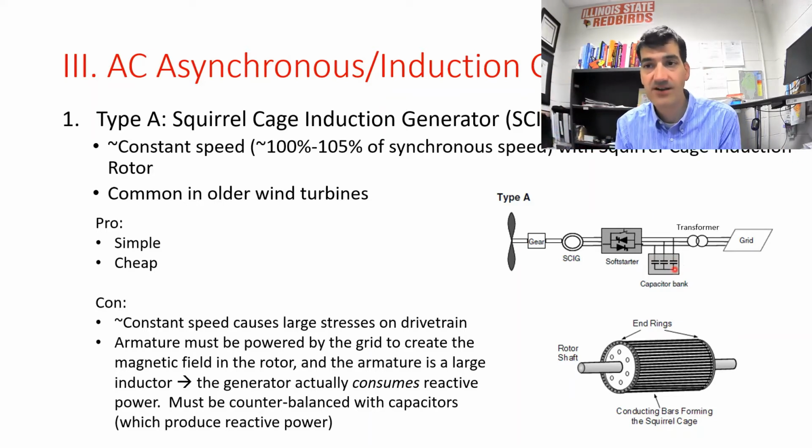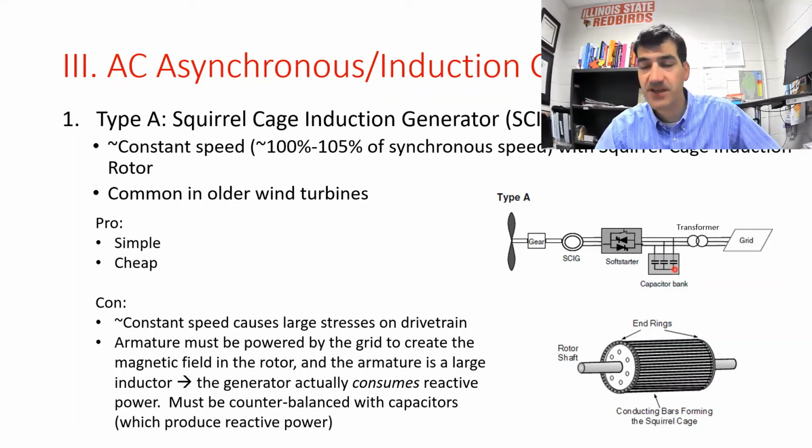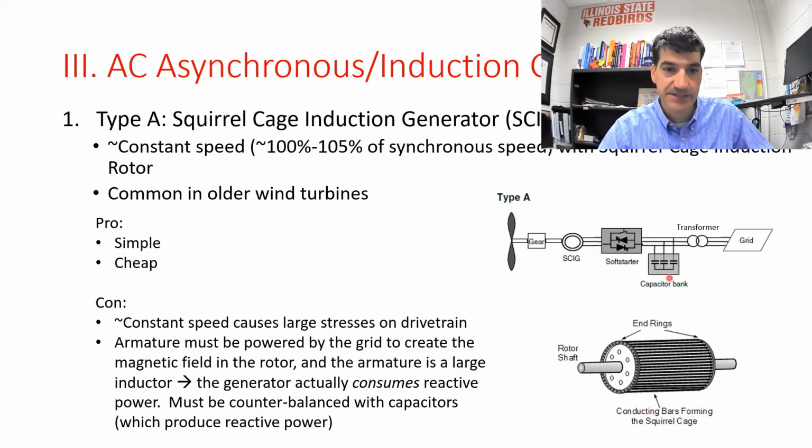But somewhere in your wind farm or somewhere on the electric grid, you're going to have to balance out all the reactive power consumed by the wind turbine by incorporating a whole bunch of capacitors. All right, so capacitors actually produce reactive power. Inductors consume reactive power. So that's why we have this capacitor bank right here.